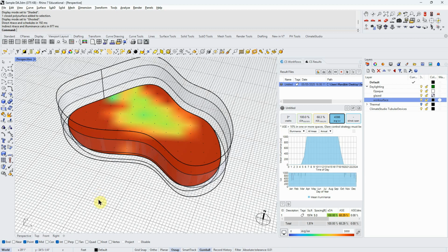Here's the other concept: when you're doing daylighting, you have to have a goal when you're designing for daylight. My goal in this little exercise is going to be to create a consistent amount of light throughout the space. This is just an example, but in the model I've made, it's a gym, and I want it to be a consistent amount of light throughout. So I need to have a target lux that I'm shooting for. You can look that up online for different surfaces. We've provided that information in different assignments.